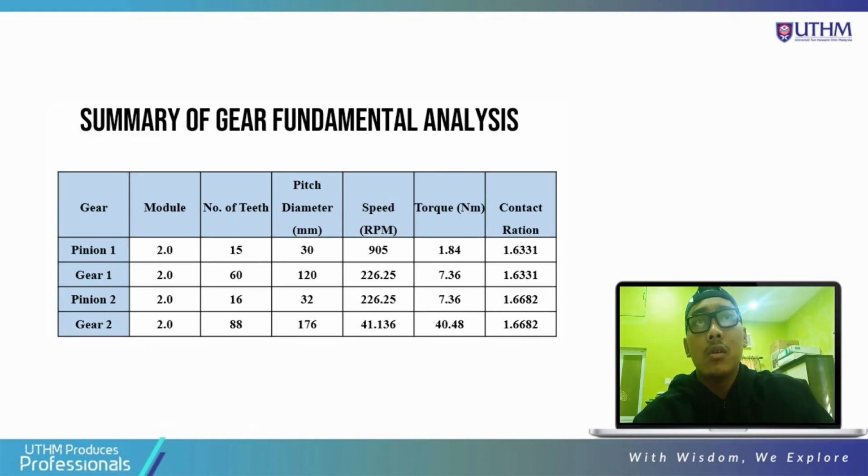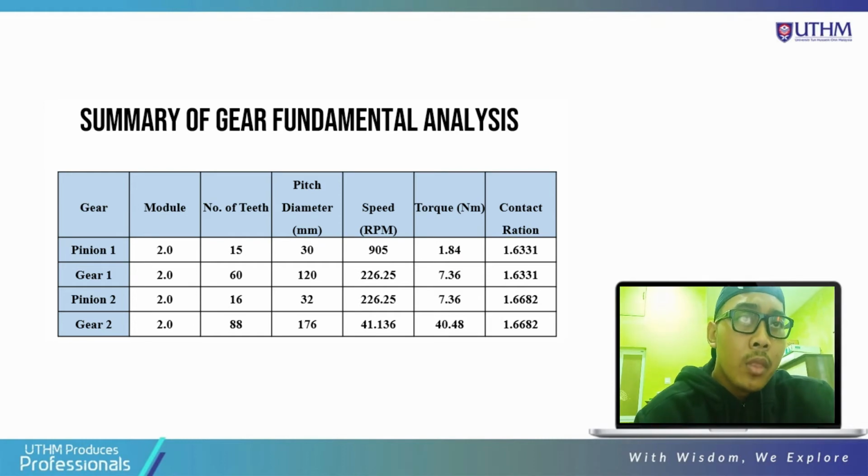Next we will go to the calculation part. Firstly, we will determine the empty bag capacity. Next, calculate the theoretical power requirement for the worst case scenario, and then determine the force needed for the pusher to push the empty bag. After we determine the force, we will calculate the power requirement for our product, because we want to choose the motor, and then the calculation of the gear set, and then selection of gear.